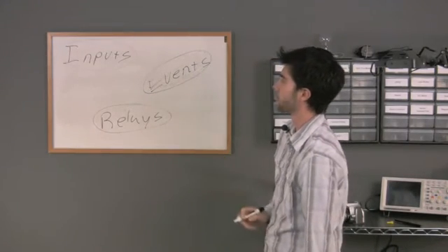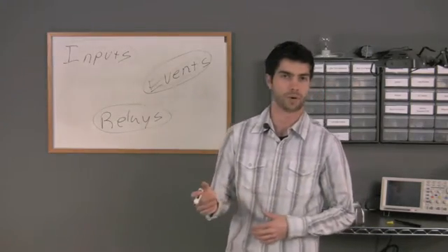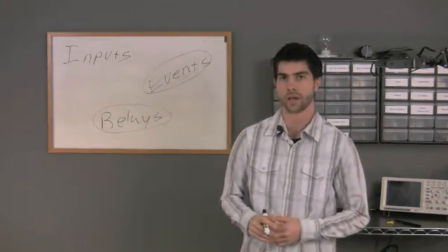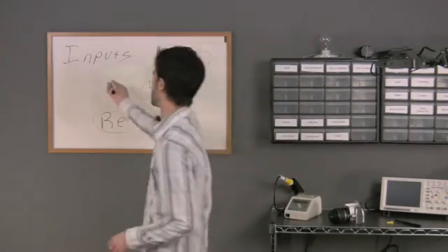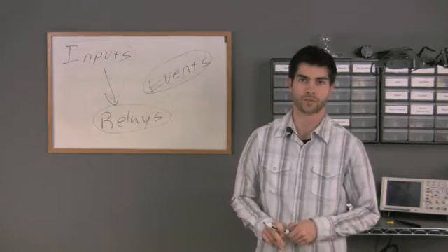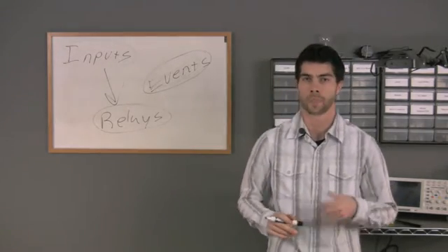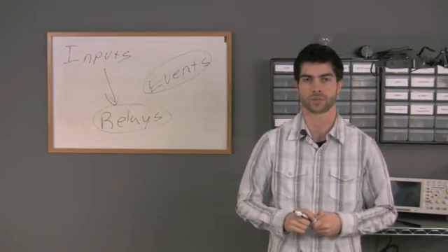So I could tell the reactor, if, let's say, it detects a button push on input 1, like we showed you, I want you to turn on a relay. That is the simplest form of reactor logic that there is. And we'll actually show you a little video here of a button controlling a relay directly.